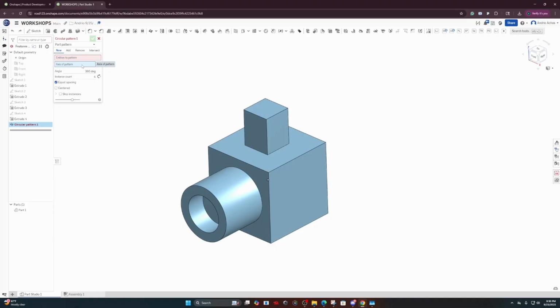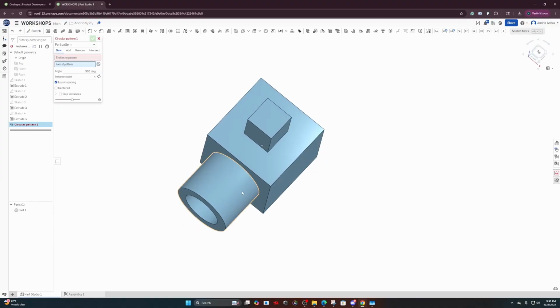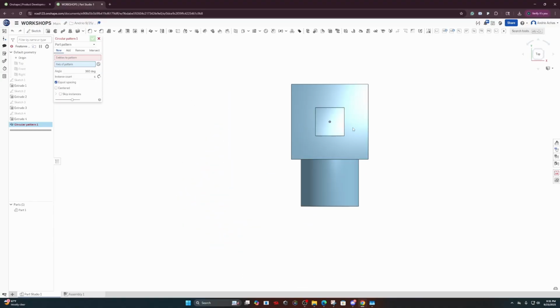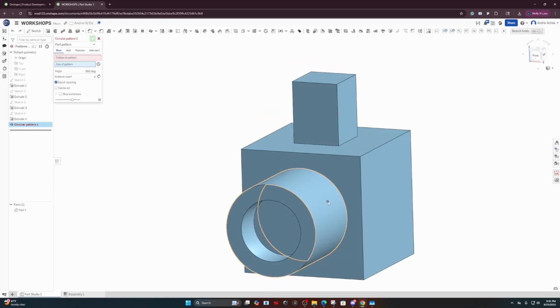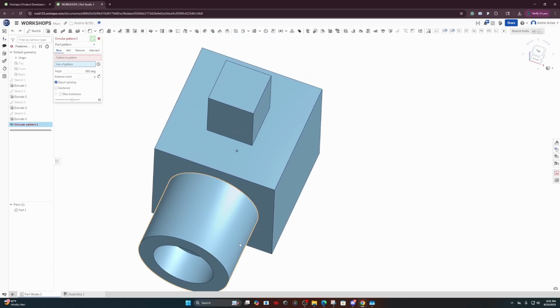If we want this thing to rotate around this cube we have, the way we do that is by specifying that the axis is in the center of this. Because it's rotating around the z-axis, we want that axis slash line to be straight and parallel to the z-axis while intersecting the middle of the box. So let's do that.